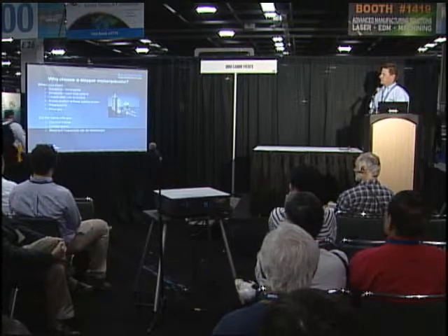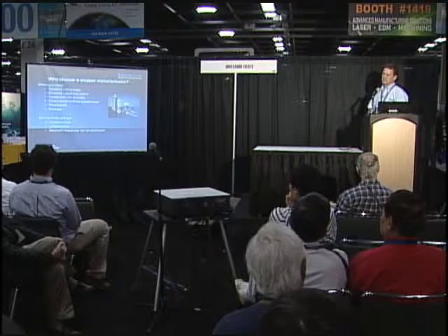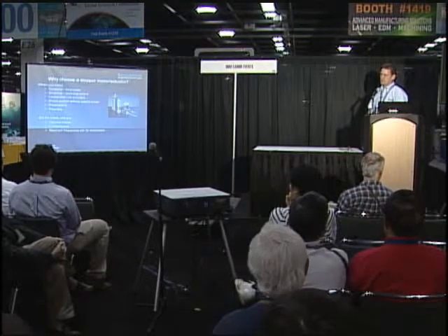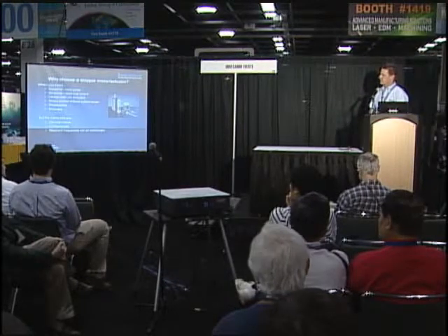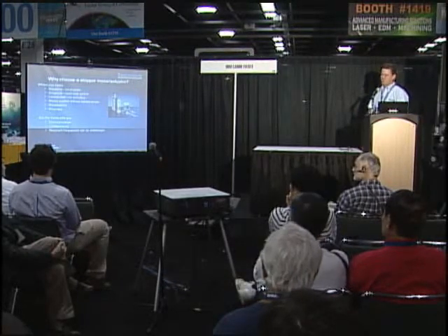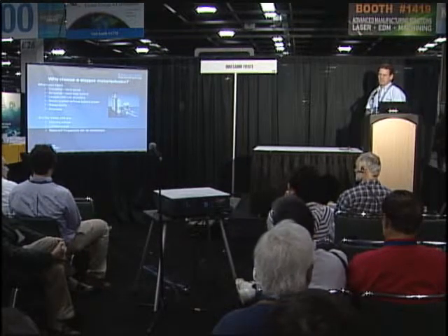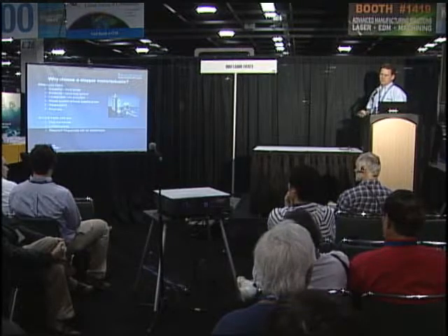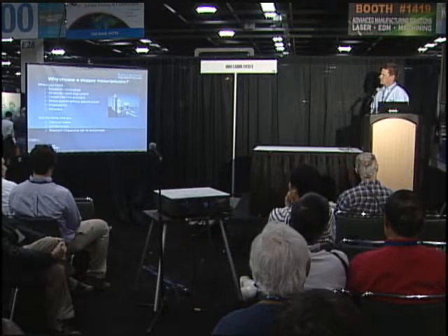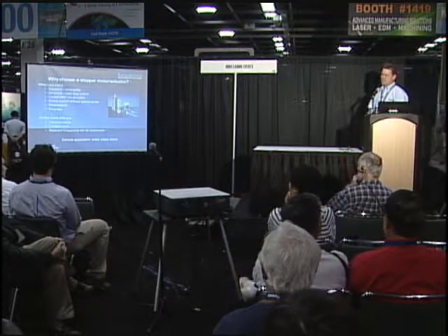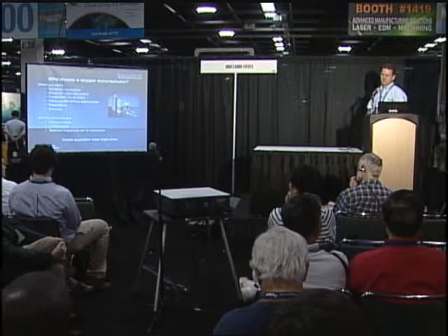The trade-offs are discrete motion, because now you have to work within the step count. If it's stepping in between an area that you want, it can be rather difficult. They're limited in speed, and the resonant frequency depends on the particular build of the motor that you're using. Those resonant frequencies change, and you also can have harmonic problems. Linear stage slides are used in that. There's a lot of optics applications that use the steppers as well.